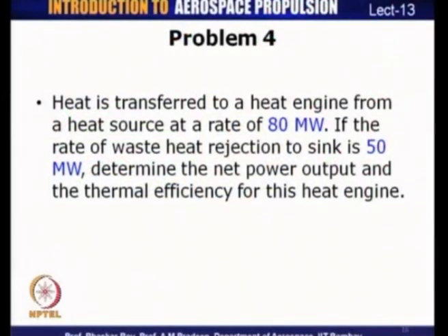Now, what we shall try to solve next would be a problem from a heat engine, and we shall find out the efficiency associated with that. So, let us look at the fourth problem we have at hand today. Problem 4: heat is transferred to a heat engine from a heat source at a rate of 80 megawatts. If the rate of heat rejection to the sink is 50 megawatts, determine the net power output and the thermal efficiency of the heat engine.